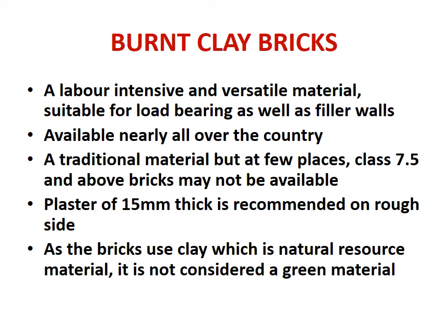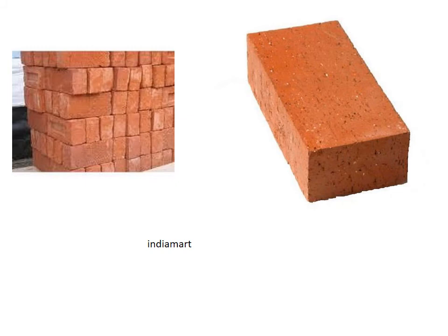Then plaster of 15 mm thick or so is recommended in case of burnt clay bricks because of the rough surface. So that is not required in other types of bricks like what we have discussed. But in case of burnt clay bricks, that is required. As the bricks use clay, which is a natural resource material, it is not considered a clean material nowadays. That's why the engineers are switching over to other alternatives like AAC blocks or fly ash bricks or recycled CND waste blocks. We know this all.